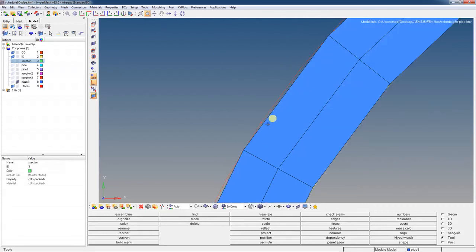And they don't really match the curvature of our circle completely. See how it's kind of a straight line in between here and here. Now, if we used higher order elements, and we'll talk about those in class later, then we can probably match that curvature a little bit better. Or if we wanted to use maybe twice as many elements, that cutoff of the curvature wouldn't look so severe. So by discretizing our structure, we're already introducing potentially some geometric approximation to what we really have.